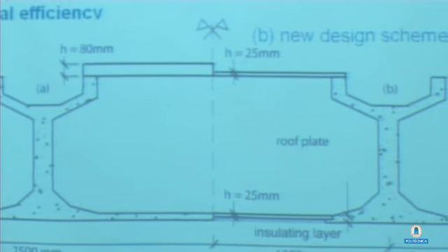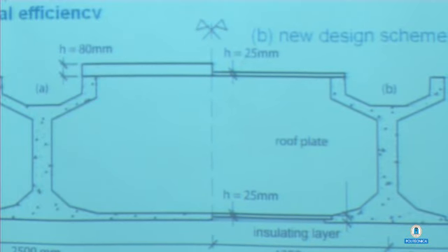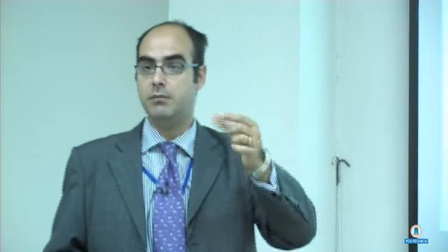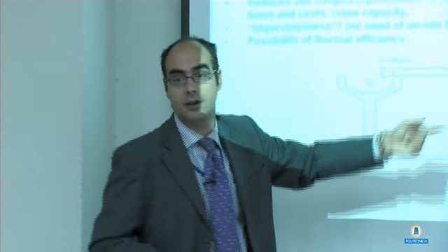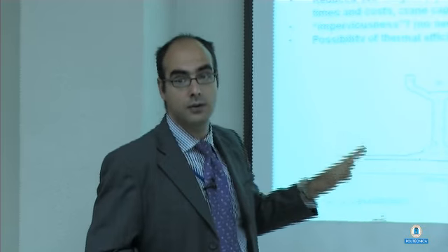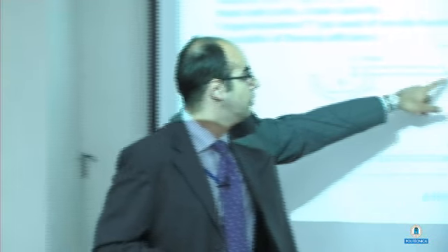And actually the traditional solution, the thickness of the slab is 80 millimeters nominal thickness, because you have to respect the minimum thickness on both sides, and you have to place some reinforcement here on the tension side. So due to these constraints, you cannot go lower than 80 millimeters. We designed a solution with only ultra-high performance fiber reinforced concrete, so no conventional reinforcement. We could go down to a nominal thickness of 25 millimeters. Actually, the results of a production test was between 25 and 30 millimeters.